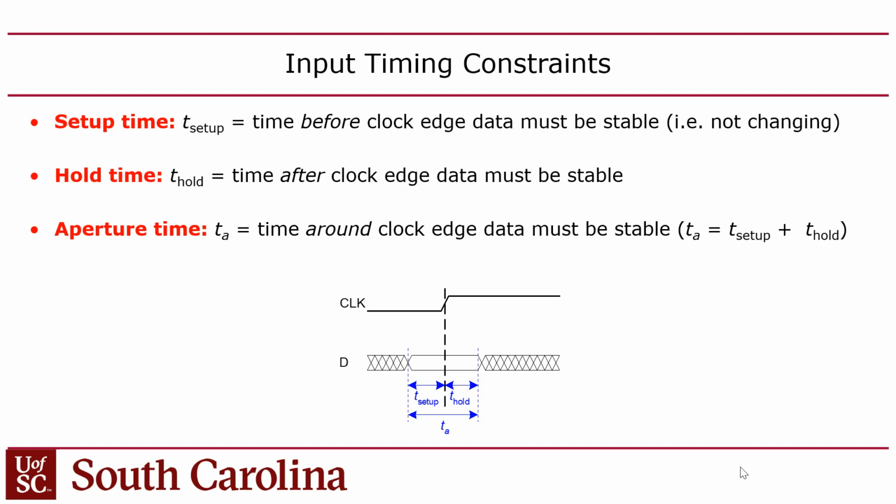Well, there's a chance that the register will become metastable, which means instead of locking in the value of D and freezing it inside the register or the flip-flop, the output will actually go between 0 and 1. Like if your voltage is, say, 2 volts, the output will go to like 1 volt. And it'll stay there for a while, but not too long, because eventually it'll settle into its correct voltage, right? So the metastability is a temporary thing.